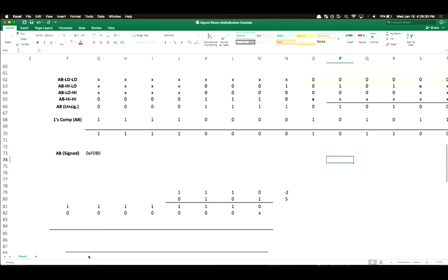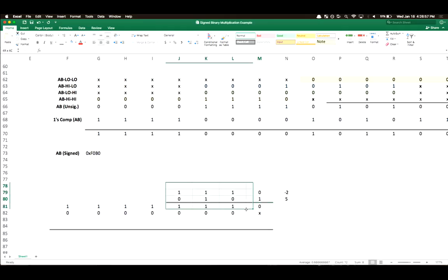Yeah, you would have to break them up. The least significant bit, this one? Yeah, that would not hold a sign. That's very true. So for this example, doing it this way, I didn't really work it out, splitting it up, but it's going to be the same thing where you're just going to have to look at the sign. But when you do it this way, we don't really care what's on the sign bit because we're just doing multiplication the regular way, and we're doing sign extension.